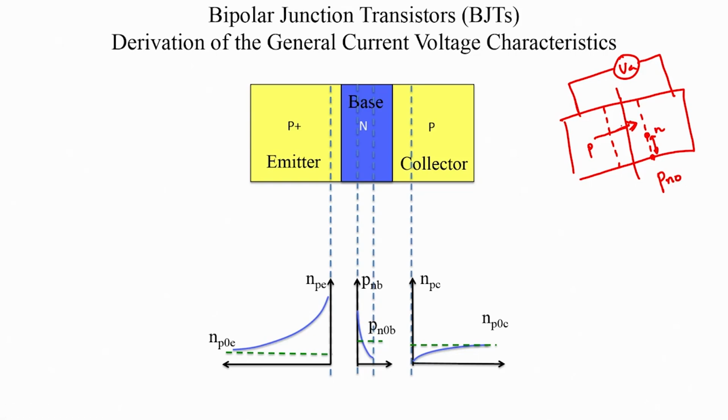And by applying a forward bias, this became Pn, okay, which was greater than the equilibrium population, and the excess injected carriers was delta Pn, which was basically your Pn minus Pno. So, that is equilibrium, that is non-equilibrium, and this is the excess due to the non-equilibrium.